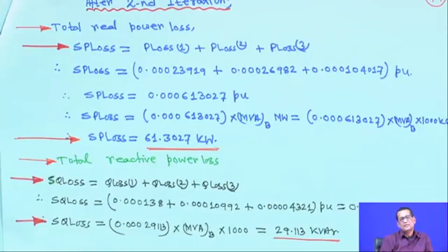One equation we wrote: Ijj is equal to Vm1 minus Vm2 upon Zjj. Another equation: Pm2 minus jQm2 is equal to V conjugate m2 into Ijj. Using those two expressions, we can also get the angle expression. But as in the distribution system voltage angle is not that important, because we have seen the variation of angle is very small, the magnitude of voltage is sufficient.